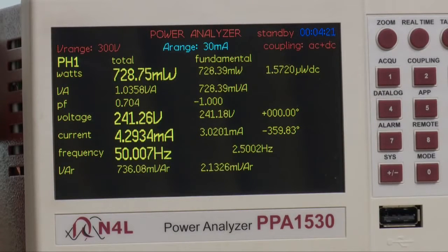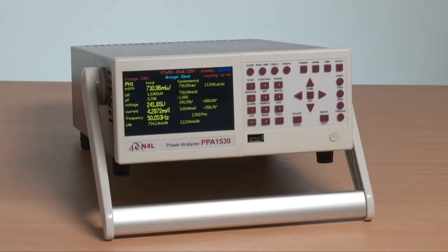And we have a steady 729 milliwatts power instead of 500 milliwatts, followed by large pulses. We therefore have a solution to switch mode power analysis of low-duty standby in one instrument, with no external shunts and with no smoothing required.